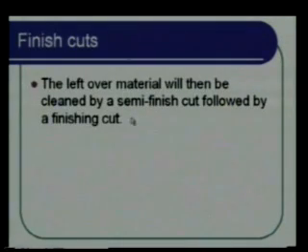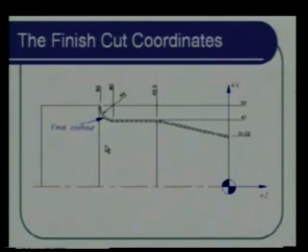Okay, now the leftover material will then be cleaned by a semi-finish cut followed by a finishing cut, 2 cuts. So I will have 1 semi-finish cut going through this and 1 finish cut, so that the surface finish of the job is going to be really good.